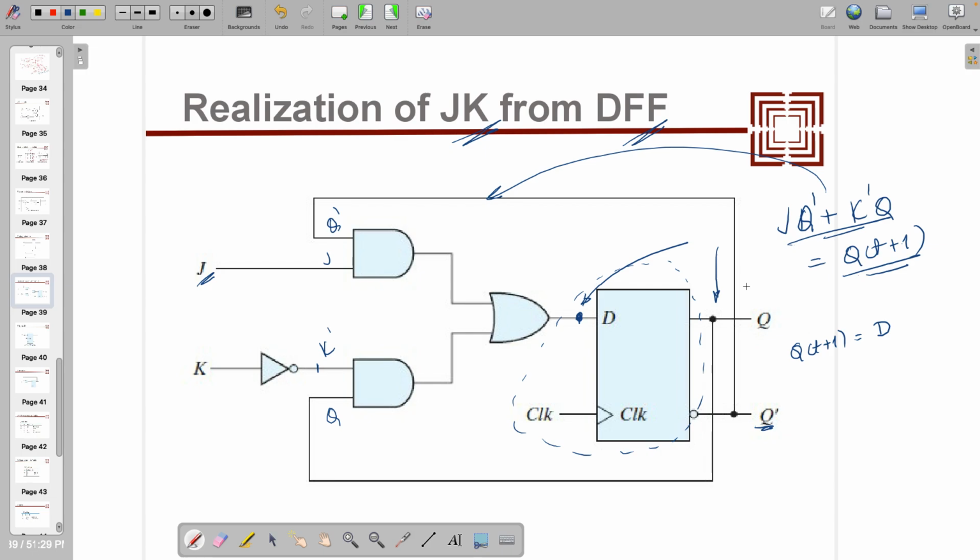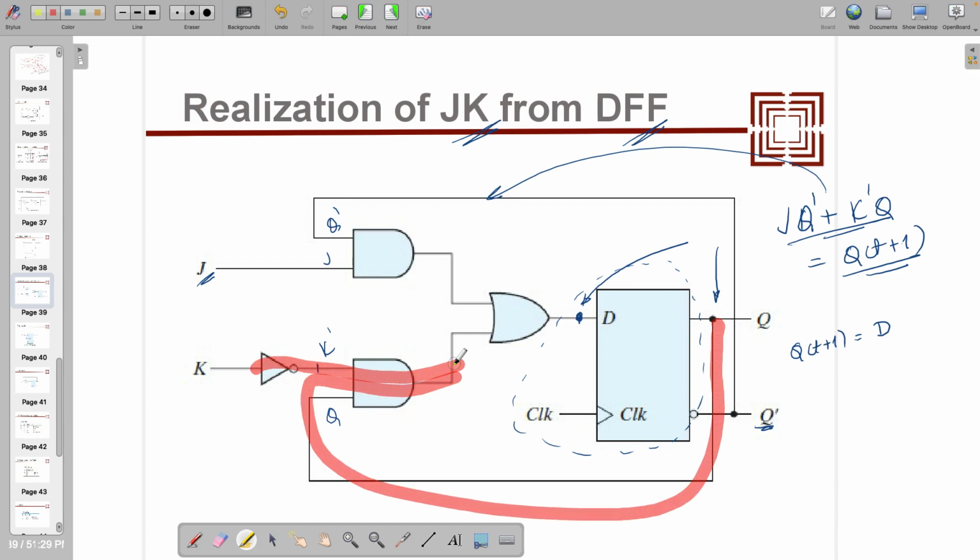In this whole process, delays will be added, that one needs to understand, right, because earlier JK has some 3 propagation delay of NAND, but now it's actually more. That needs to be taken into account. Here actually on the critical path, these things will also come, right, that needs to be added.